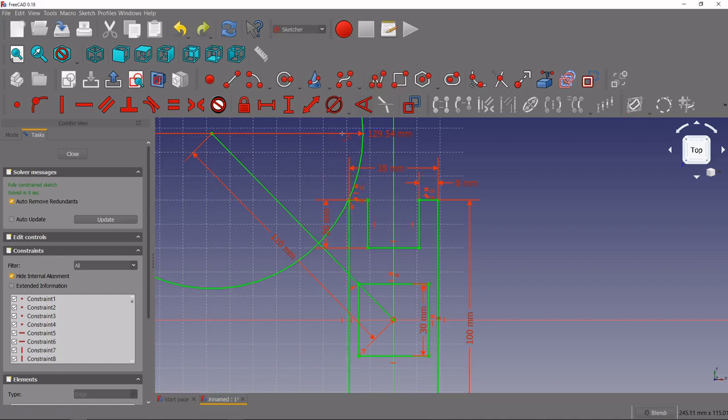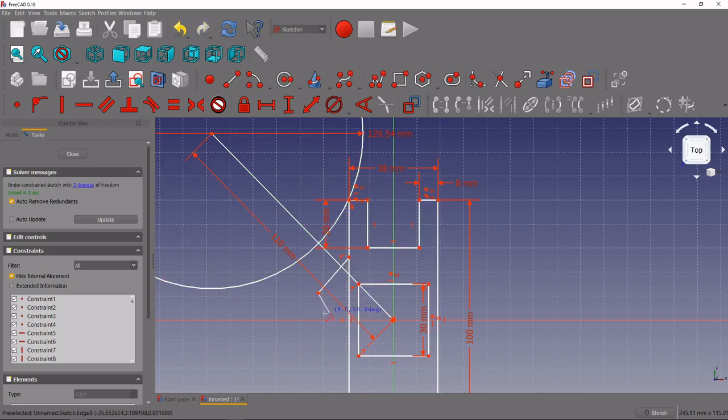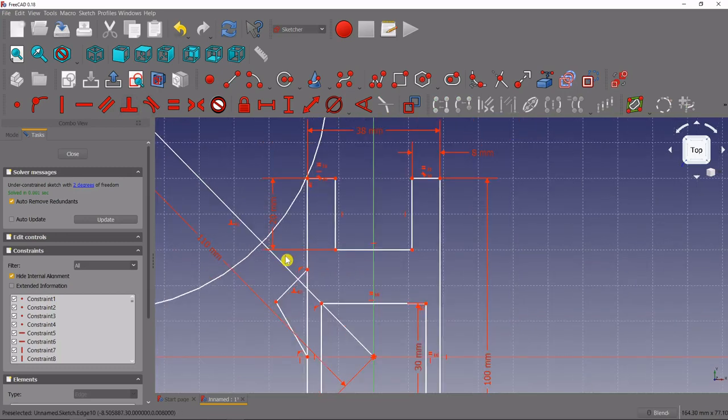We can select our polyline tool and just make sure we get those constraints on there. And we're going to first constrain this to the x-axis, and then we'll left click a couple of times to exit the tool. We'll select our endpoint and the vertical line of our bottom plate body, and we will use the fix onto constraint. Another thing I like to do is always make the arm perpendicular to the little area we're making here for the mounting holes. So we can click these two lines and use the perpendicular constraint. And another thing we can do is use the symmetric constraint to make sure the arm is always in the center.